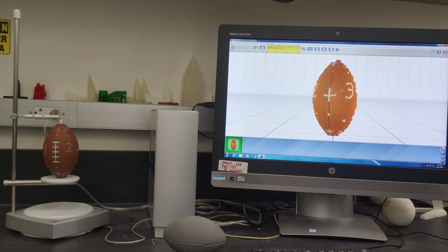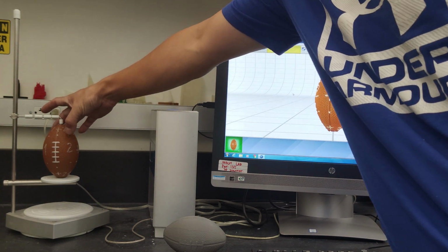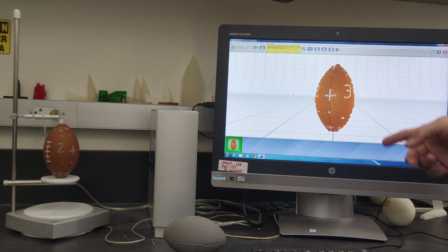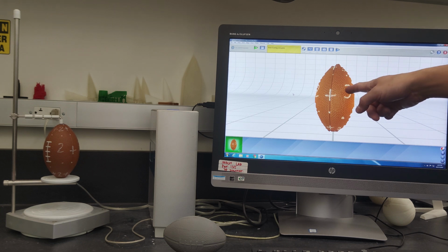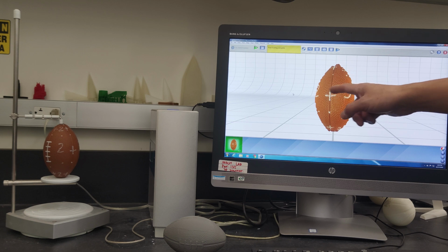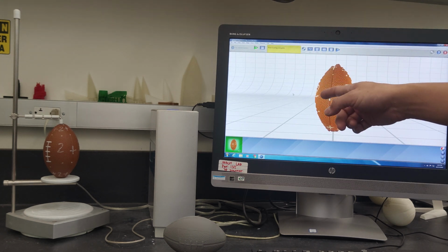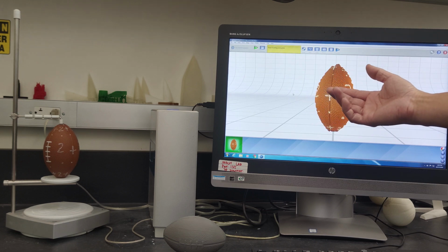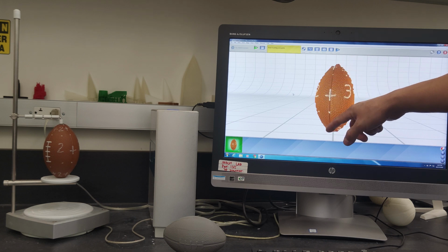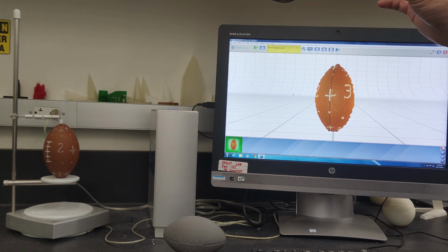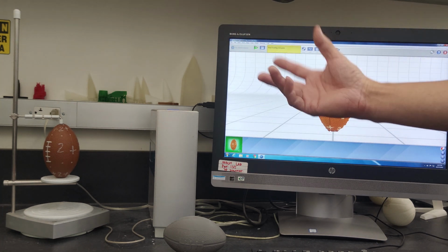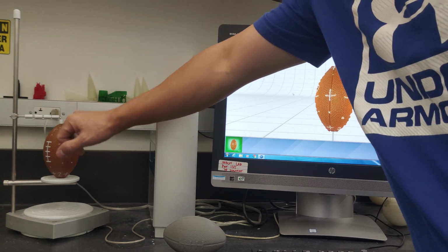Alright, now we can manually switch the direction of the object, then scan the section next to the previous one. Then after we get the new surface section scanned, we will drop some pins, like reference points, onto the two sections. Then the software will know how to combine those reference points together, then generate the final model.